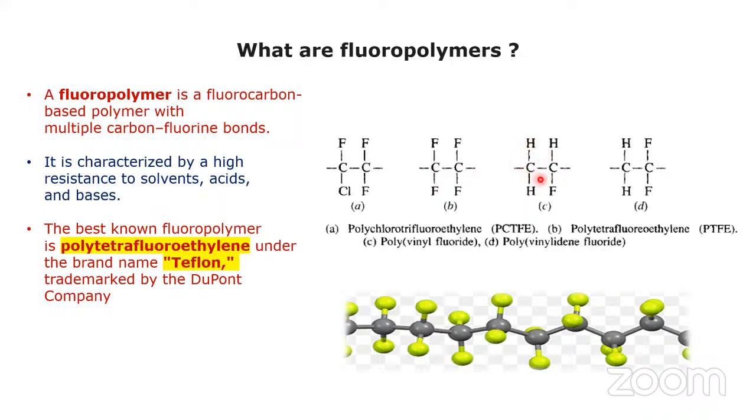That's why it can be affected by external stimuli, whatever the heat and chemicals are there. It can be affected. But if you have only fluorine and carbon bonding, it will not be affected easily. And that's why the cracking you are mentioning was observed if you have fewer fluorine atoms in your polymeric system. And chlorine content will create rust in any metal. So, yes, only B can be used for that coating purpose of spring.